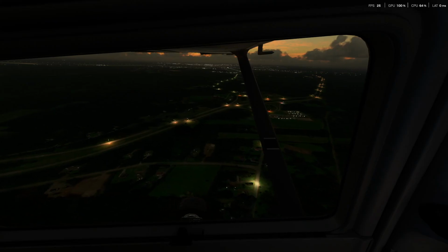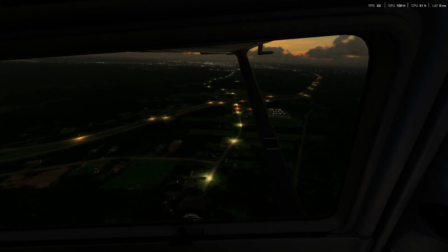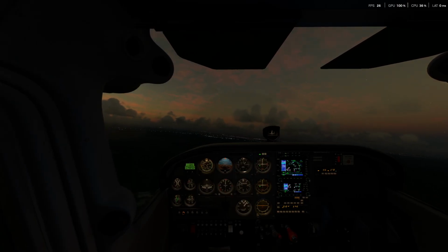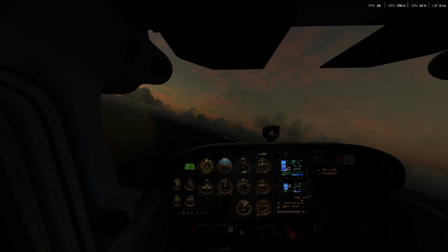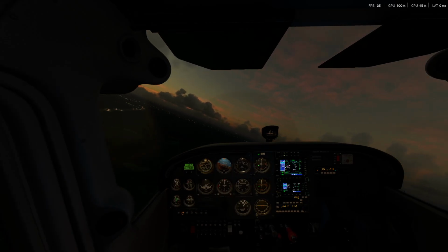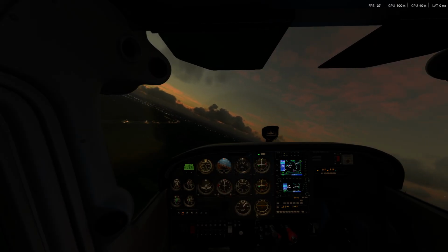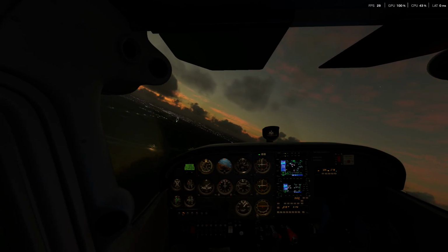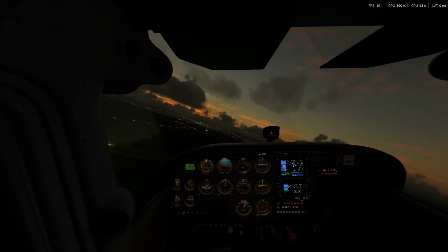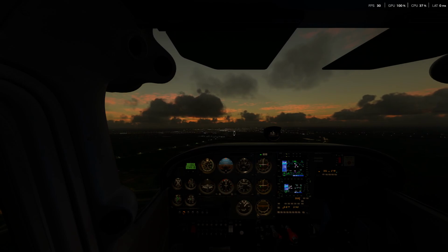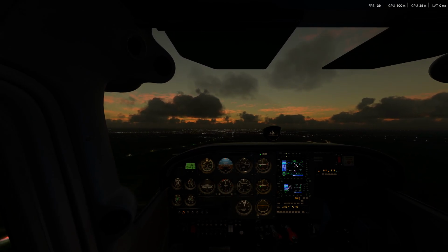And wind is pretty low. Next, there's runway 29, so we're going to go ahead and turn base. So we'll turn final here just shortly. We'll go ahead and make our left turn here now. Pushed out just a tiny bit, but we're not going to increase our turning rate. We're going to just maintain about a standard turn. So we'll track that center line. I'm going to go ahead and pull back a little bit on the RPMs.